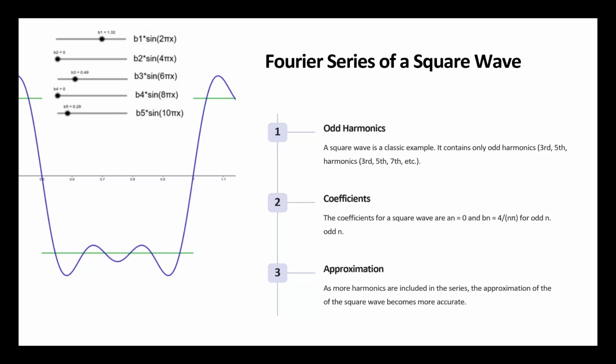But the short answer is the symmetry of the wave. Let's dig into that to get familiar with the reason and what the behavior of the Fourier series is based on the waveform of our actual voltage. Now, besides that advantage, which basically helps us a lot on controlling distortion, because it automatically gets rid of half of the harmonics, all the even numbers are gone.